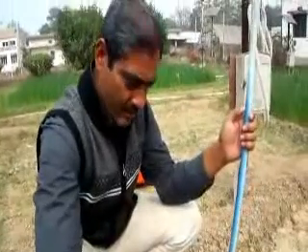That we can calibrate. I will give you the calibration curve to find out the moisture content in terms of the hydraulic head we have measured in the soil. So you can find out that at this particular hydraulic head, this is the moisture content of the soil. Then you can compare with the other two methods, the gravimetric method, which is the basic method, and the FDR method.